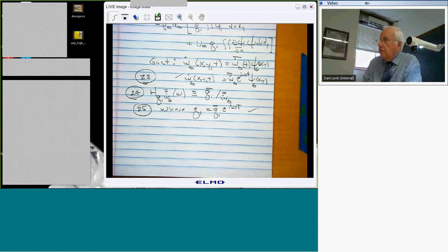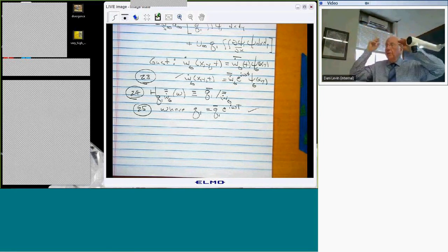It's the frequency of the gust, but for sinusoidal input gust and a linear system, what's the frequency of the motion? It's equal to the gust frequency after the transient dies out. I mean, we're thinking of steady state here, right? If you're thinking in physical terms, if I turn on the gust with sinusoidal characteristics in time, there's a transient in terms of the motion of the wing, but eventually if I wait for the transient to die out, I'm in a steady state oscillation where the gust input frequency and the structural motion frequency are the same.